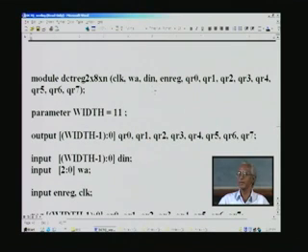For example, with the arrival of the first clock, you will route it to QR0, and then divert the next data at the next clock to QR1 and so on, and at the 8th clock you will input into QR7.